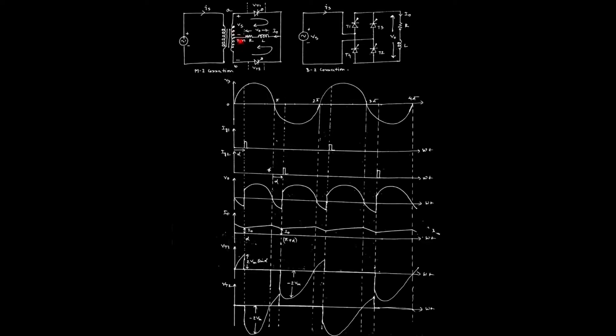Immediately the voltage, constant in magnitude with respect to Vs, is followed by the load voltage. So the load voltage is reflected from the negative half of the supply voltage. That means the positive half and negative half are both in the same direction, which is why we can say it is a rectifier operation. But due to this inductor, there is always an extension part over here due to the discharging path. This is the output voltage waveform across the load.